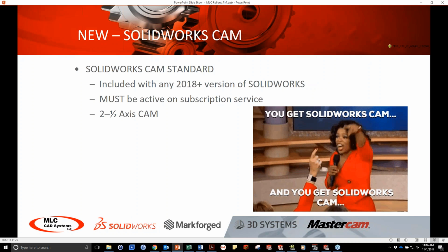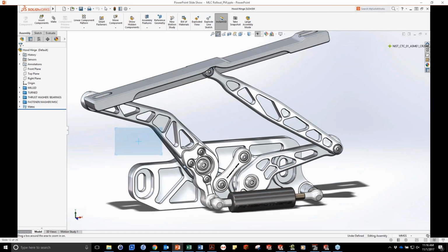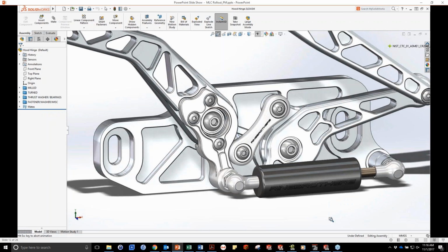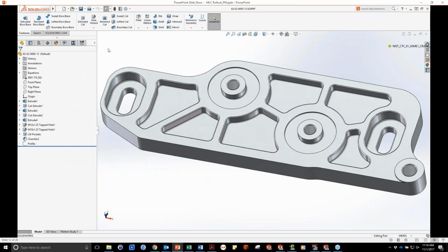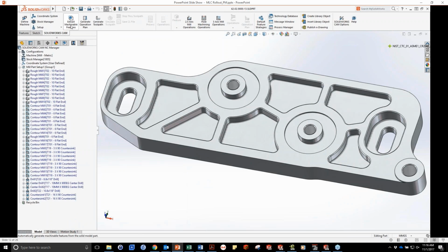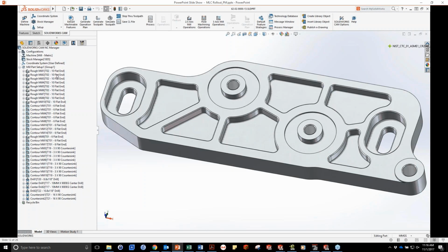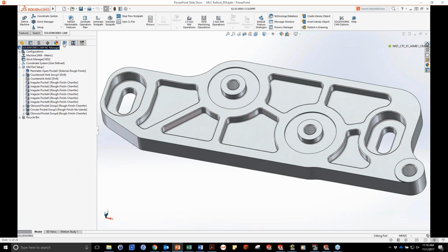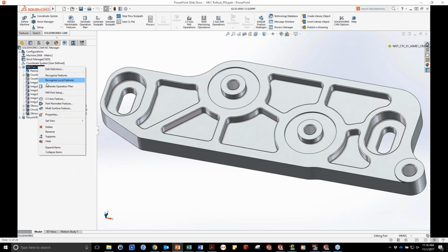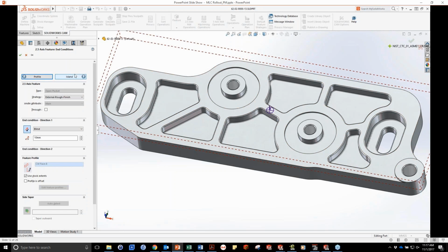Now, I'll show you a little bit of what this looks like inside of SOLIDWORKS. I have a video, and I know they've been a little blocky, but I'll pause it a few times. What I want you to see is that this is in the same interface that you already know how to use. This uses automatic feature recognition technology, plus it uses some manufacturing best processes and some rules that you've already set up to determine feeds, speeds, step over sizes, all that kind of stuff. When you get done, you get a tree. You can manipulate it, add more things to it if you need to. You get to work directly with your CAD file and your different configurations. So you shouldn't have to make any reference geometry like additional sketches to add what you want.